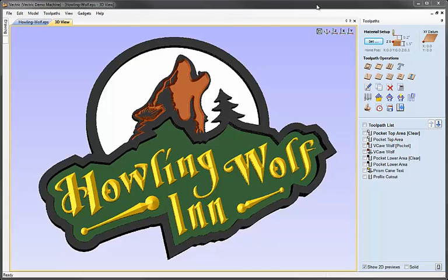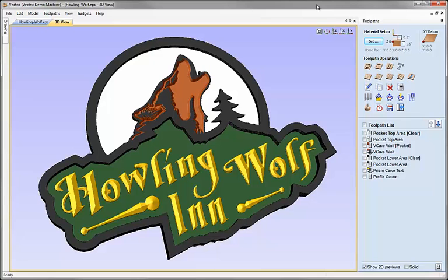In creating our example, we've generated a number of different toolpaths that use a variety of tool shapes and sizes. When we come to output these for the CNC machine, we want to try and minimize the number of files that we save. We can do that by appending toolpaths together that use the same tool. If you have an automatic tool changer, of course, then you can actually save everything in a single file as long as you've assigned appropriate tool numbers to each tool as you are calculating the toolpaths, in which case that will automatically do the tool changing for you. For anybody that doesn't have an automatic tool changer though, you are going to need to save separate files, one for each tool.